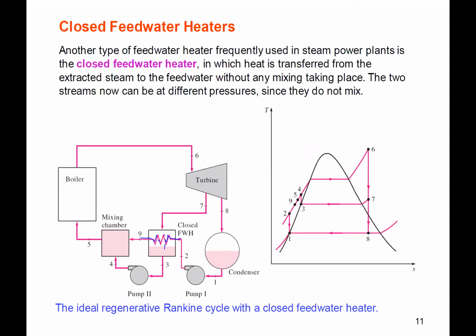All right, so when we work our way around, we get 1 inlet to a pump. But the big thing in this diagram you see is this 1 raises it to pressure 2. Pressure 2 is the same as this pressure, which is a mixing chamber, which means they're all at the same pressure in the mixing chamber. So they're at 5's pressure. That's the max pressure. So that's all along that max pressure. So we went all the way up to that max pressure with pump 1.